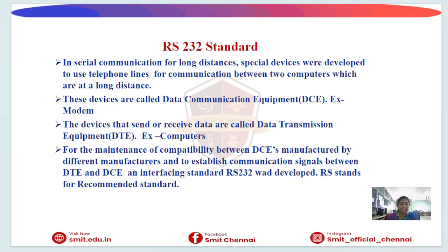Before class, we discussed these components. The 8051 uses TTL voltage levels, while RS232 uses different voltage levels. TTL means 0 to 5 volts. RS232 levels have to be changed to TTL, and TTL has to be changed to RS232, so the MAX232 is needed for the voltage conversion.